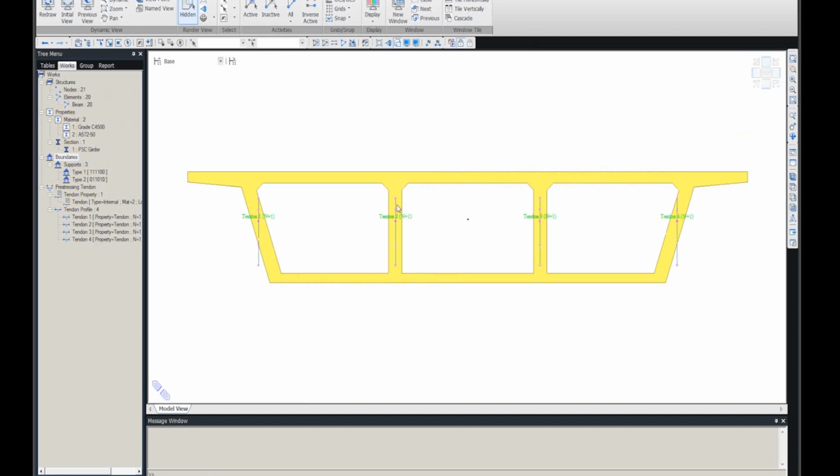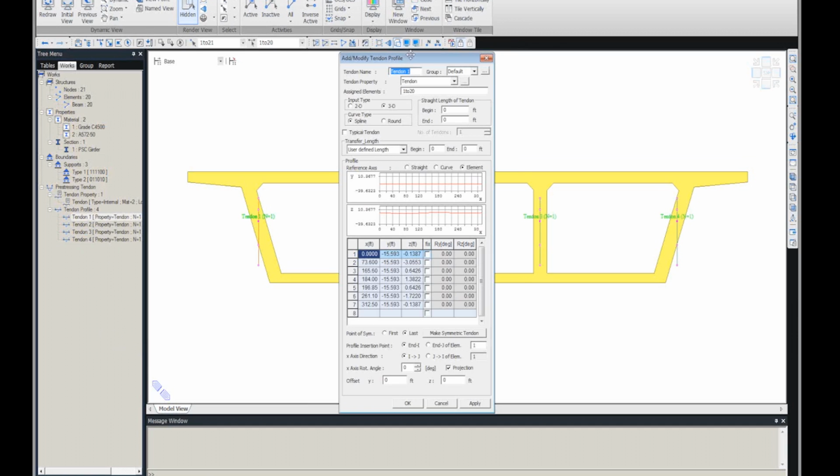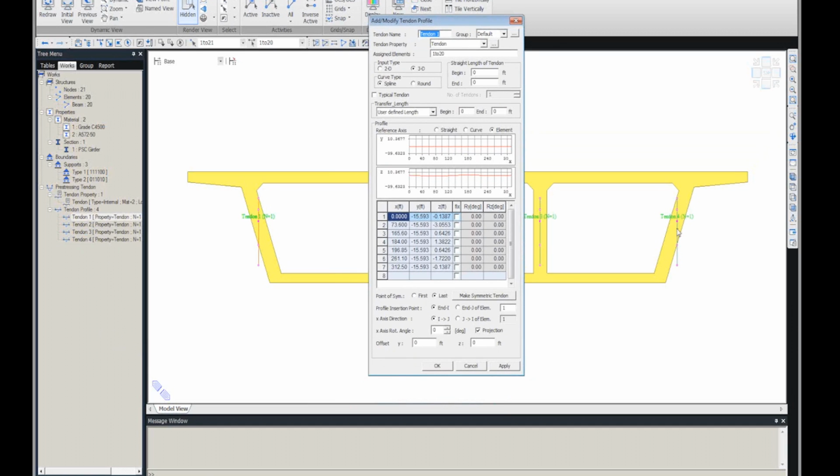See, here is the thing. We got this tendon profile correctly for these 2 webs in the middle, but for the side webs, because these are like angled, these ones are not going through the right direction. Therefore, we have to change this. How to change that? Midas tool is actually giving you an option to rotate the tendon profile, and then it's possible to do it for the inclined webs. So how to do that?